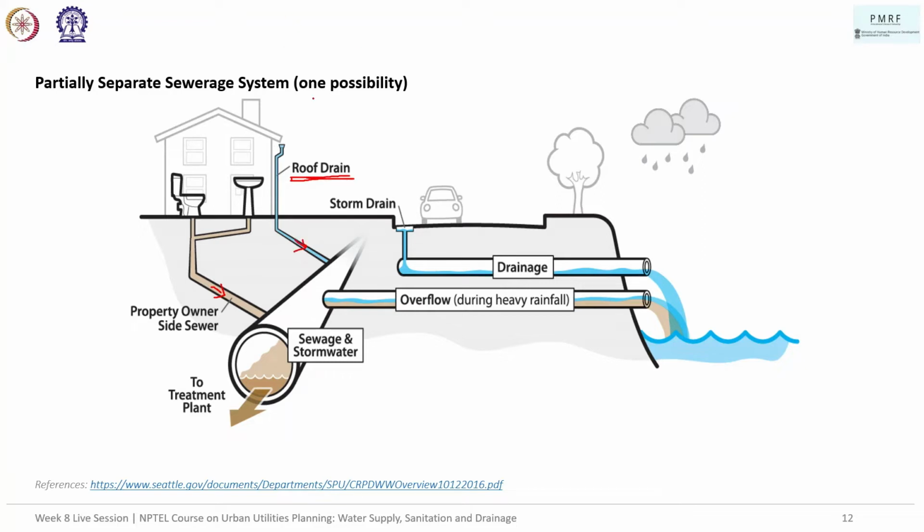So in the event of rainfall, this sewerage system gets cleaned, right? And in case of heavy rainfall and there is an overflow, it allows for the STP not to be overwhelmed. Imagine carrying this much water and treating it, so that the sewage treatment plant is not overwhelmed. We have an overflow mechanism where the excess is let into the streams.